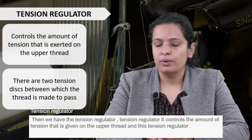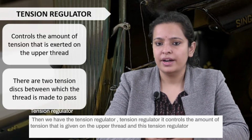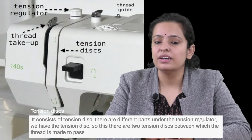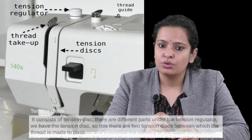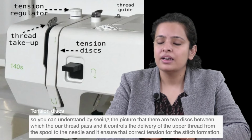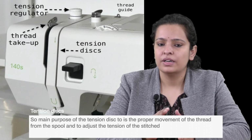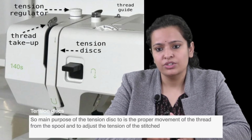Then we have the tension regulator. Tension regulator controls the amount of tension that is given on the upper thread, and it consists of different parts. We have the tension disc. There are two tension discs between which the thread is made to pass. You can understand by seeing the picture that there are two discs between which our thread passes, and it controls the delivery of the upper thread from the spool to the needle, and it ensures correct tension for the stitch formation. So the main purpose of the tension disc is the proper movement of the thread from the spool and to adjust the tension of the stitch.